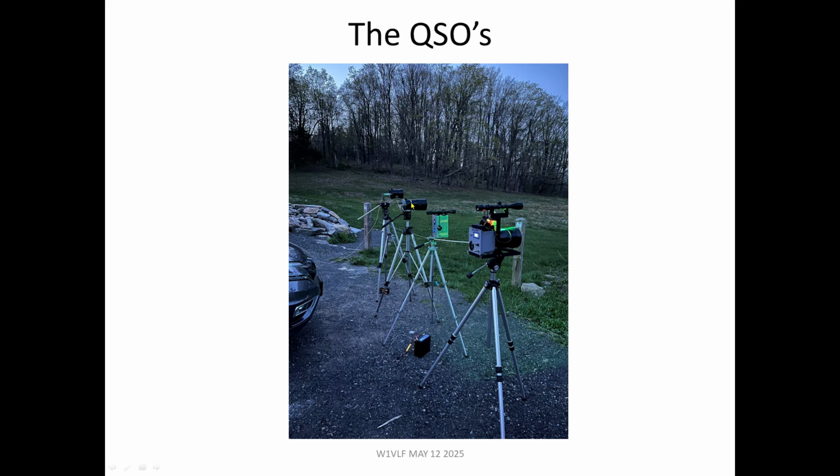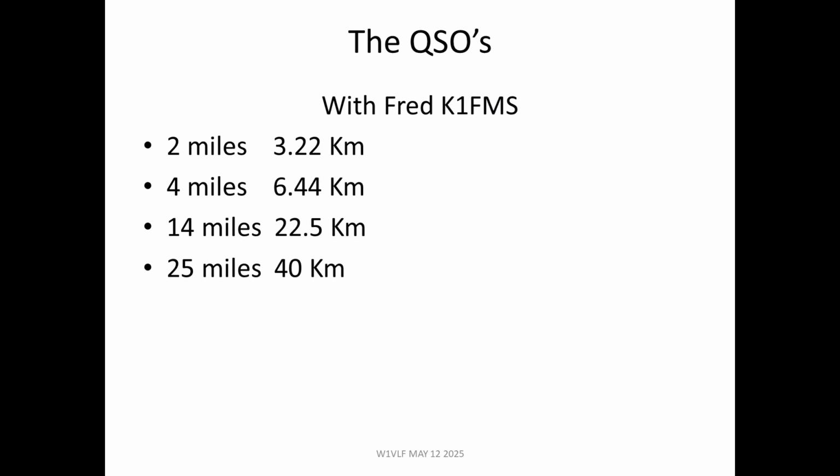That's one of my receivers with the photodiode, and then the one on the end here is the avalanche photodiode amplifier combo hybrid, and the same lenses are in front. This one has a lens cover on it, or a lens shield. That receiver running the APD is at least 20 dB better when it's quiet or at night.